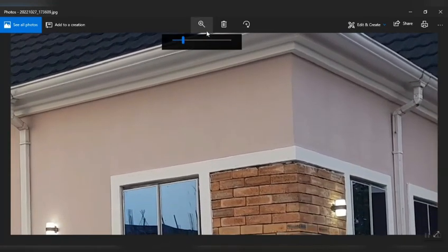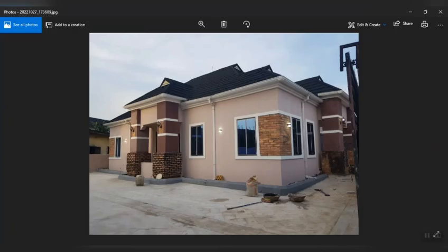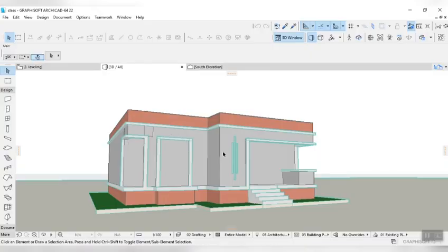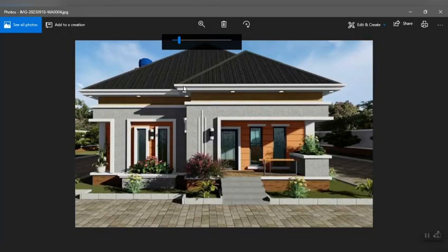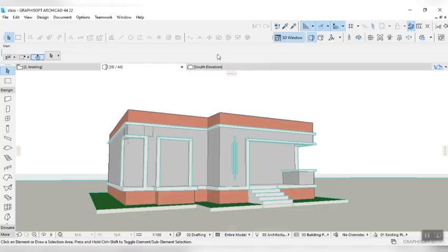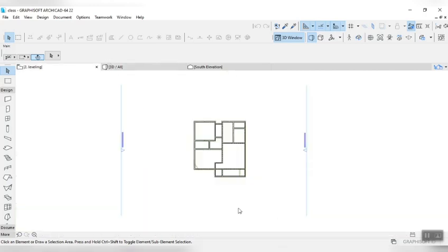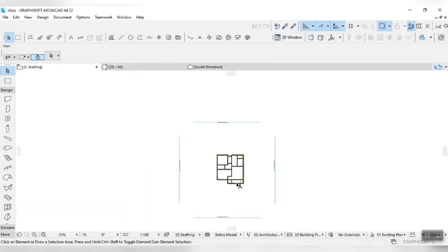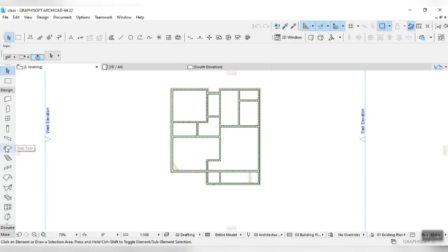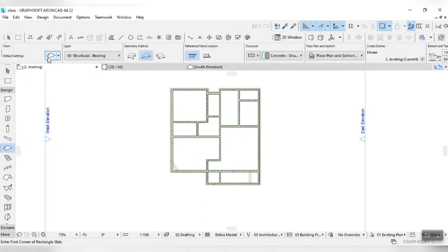So guys, we're going to be using the same method to create our slab, our concrete fascia, on this right now. This is what we're going to be doing. The first one is 300 millimeter, then the second one should be 100 millimeter, making it 2-step because of the water connector. So let's go. Come back to your leveling. This is a simple slab tool. Like I said, this is what we're going to be using. We'll come down to our slab layer. We'll go to our slab tools.